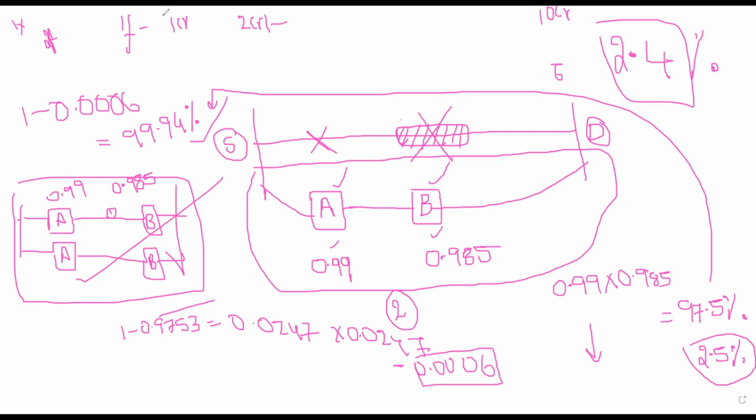So how much are you losing? 1 crore for the failure. So what does this depend upon? Repair cost. The repair cost won't be in your hands. It will depend upon the equipment. A CT will cost 5,000 rupees. A transformer will cost 5 lakh rupees. An LA will cost some thousands of rupees. So there is some factor which is influencing it more and more.